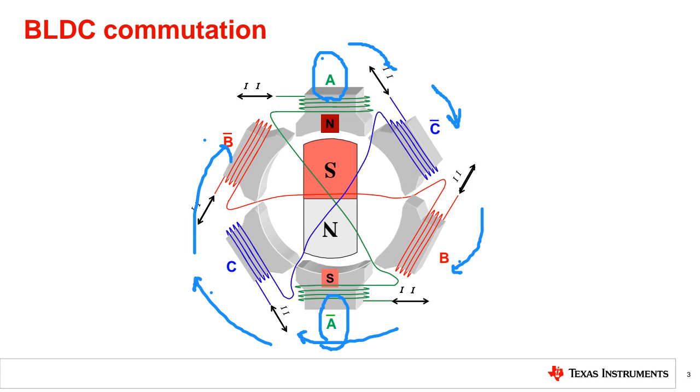While the brushes on the brushed DC motors result in less complexity for the motor drive electronics. Actually, if you need to design a very cheap application, you need to use a DC motor, because a DC motor is very cheap. It doesn't need any complex electronic circuit. You can build it using a very cheap IC and microcontroller. However, in a brushless DC motor, you need to design current feedback, position feedback, an advanced microcontroller, also some MOSFET drivers, MOSFETs, etc.